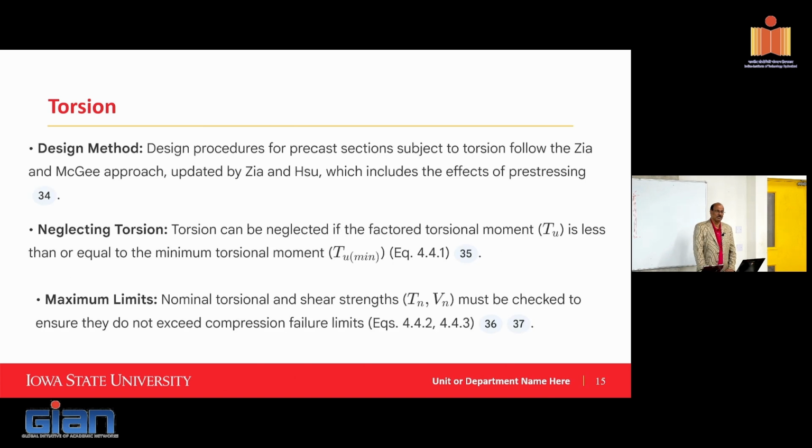There's also a maximum limit. If you're going to have significant torsional cracks, they will basically force you to change the section. So you pick a section based on your design load using the catalog. You say, okay, this inverted T is going to work for me. The reason we do this calculation is so that you can evaluate whether you are going to have significant torsion in the beam, because that's what the precasters chose to use as an erection sequence.